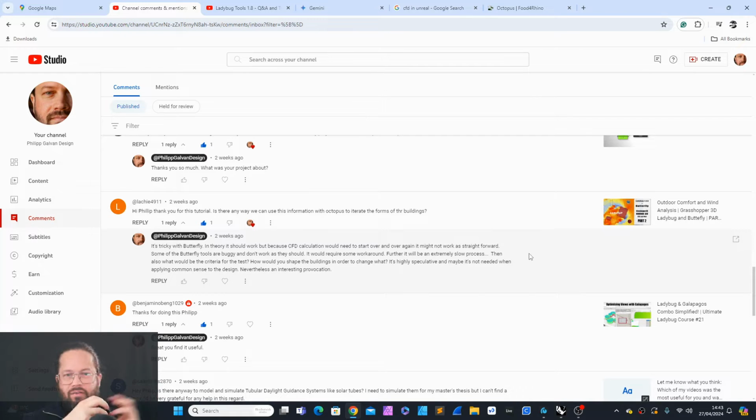And if you think about positioning a building on a site, how would it influence the site, either positive or negative? The wind is a third component which actually allows you to dive a bit deeper into that and see where could be a problem with wind tunnel effect, or sometimes this is actually good because it gives you a breeze and it cools you down.